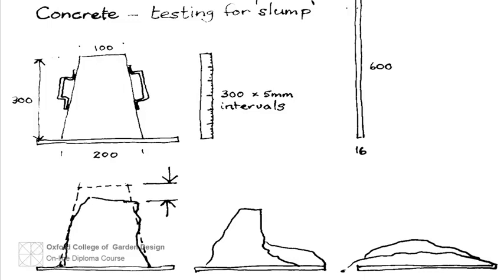Rusting of reinforcement is controlled by the alkaline nature of new concrete. This alkaline protection slowly disappears over a period of years as the concrete combines with atmospheric carbon dioxide from the surface inwards. Provided the steel has at least 25 millimeters of good quality concrete cover, then a reasonable rust-free life is assured.